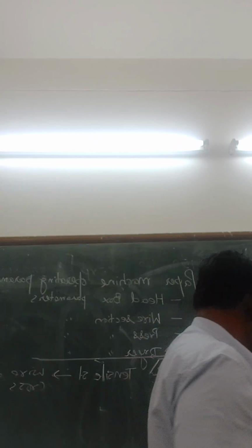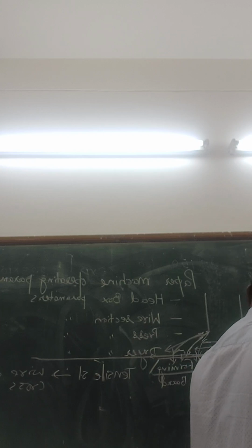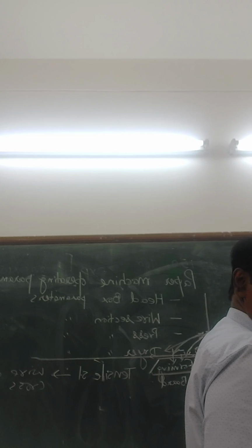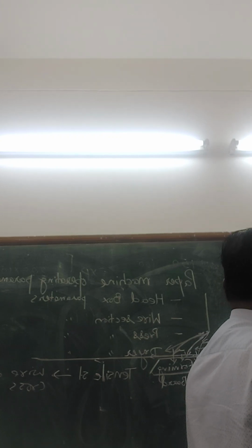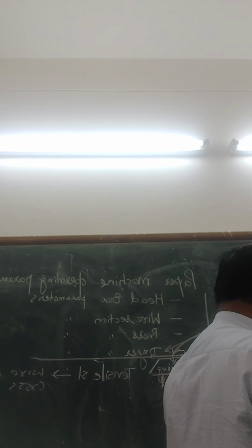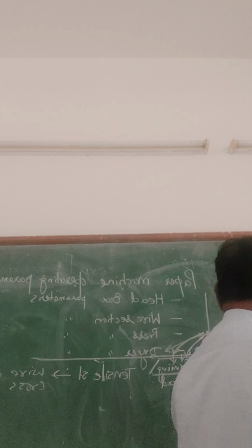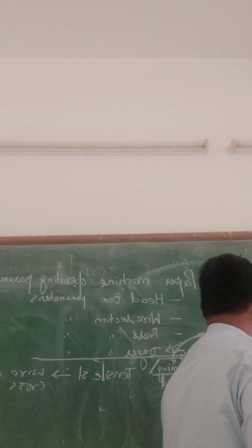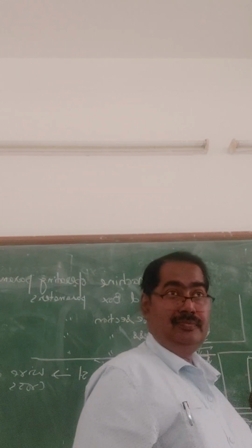That means this is a sample paper here. You can take the sample here. First of all, you can cut in this direction. You take the sample in this way. Second one is, you can take the sample like this one, in this way. For example, this is the direction of the machine in which the wire is moving. This is called the machine direction sample. Right? And this will be called the cross direction. So all the paper manufactured will have two directions: one is the machine direction, another one is the cross direction.